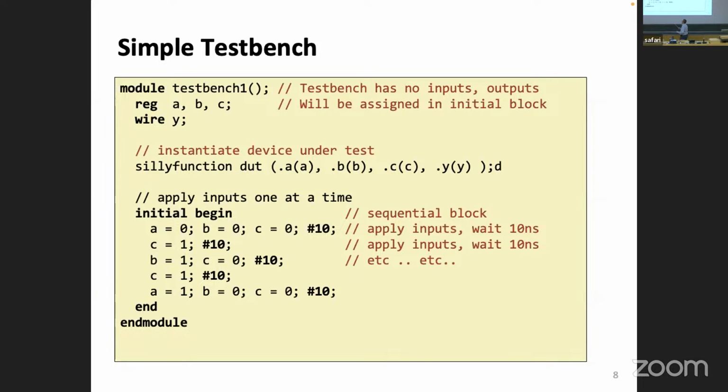Okay, we are going to get complicated. Now, I make my assignments. I say A0, B0, C0. Notice that now there is no excusing it anymore. Now I have to use blocking statements. There is no more blocking, unblocking controversy. The nonblocking assignments would be made at the very end. However, I'm doing this because I want an ordered number of events.